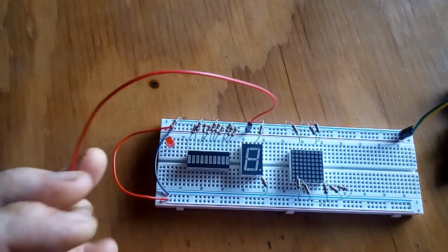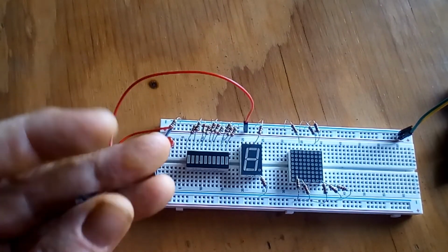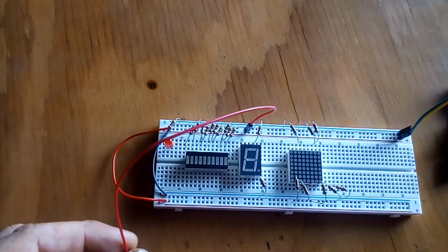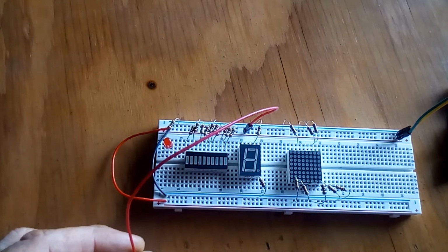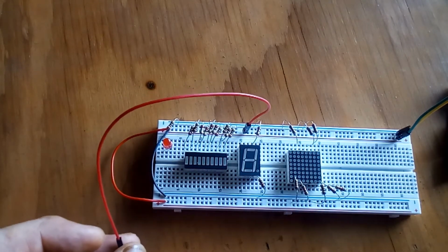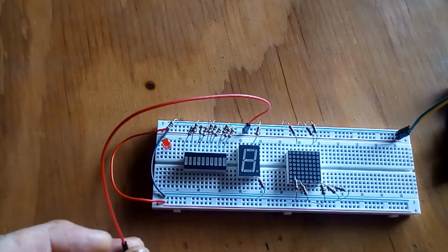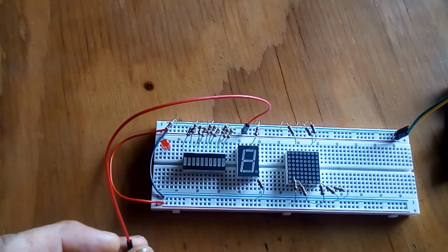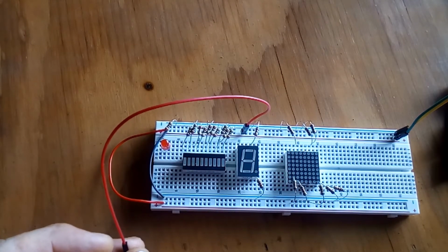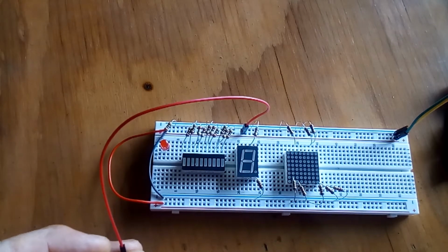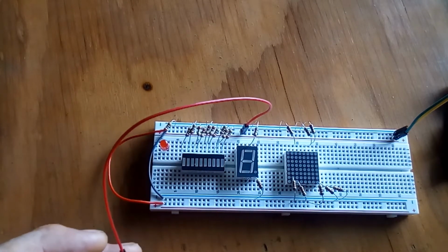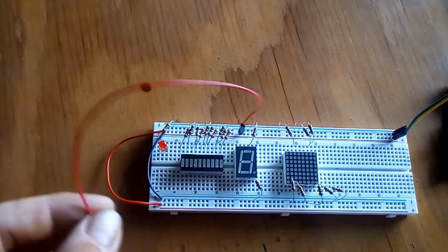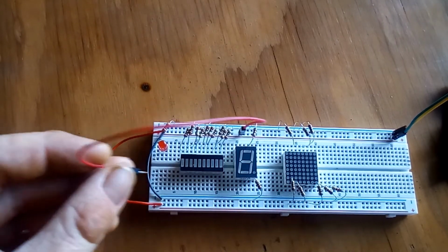And you might be thinking, if you watch that video, but didn't it take 3 lines? And yes, it took 3 lines, but 2 of those were clock signals. And clock signals synchronize things, so those clock signals are going to be used at, say, every register. So if we had 20 registers, we'd need 20 serial lines, but we would use the same clock signals to synchronize every single register. And most of our components need synchronized together, so those clock signals can be used elsewhere too. So the clock signals are just kind of something we have to have if we have a bunch of components. But basically we can control 8 outputs with 1 input using registers.